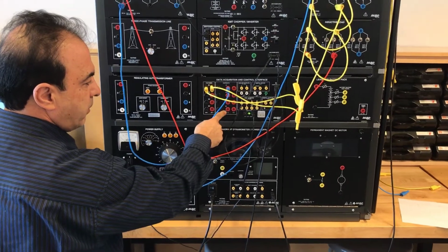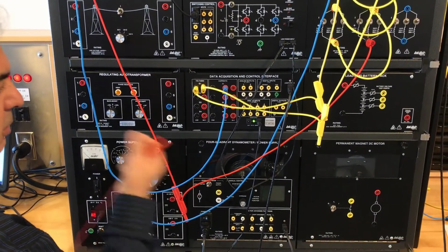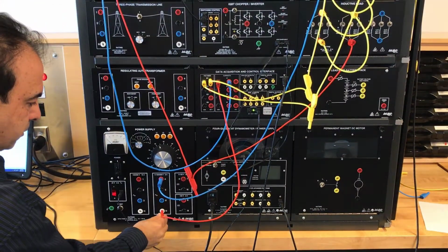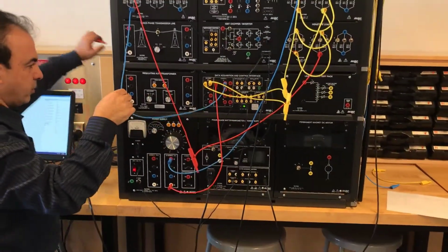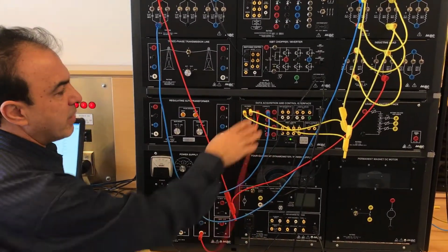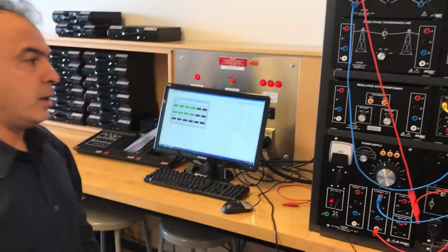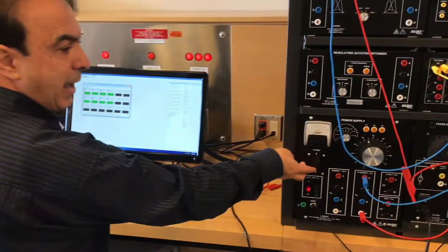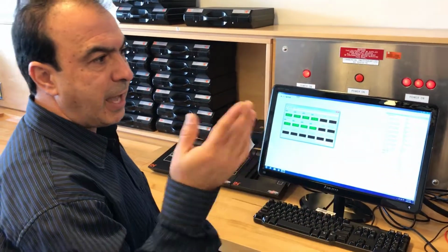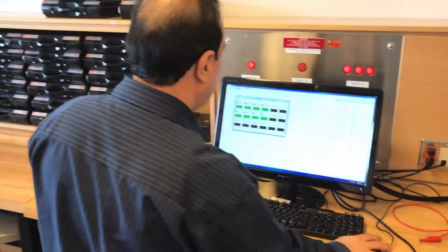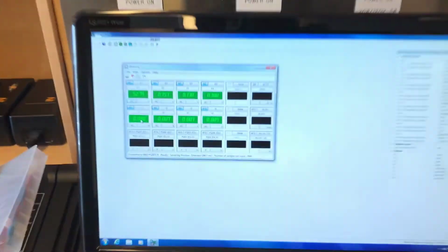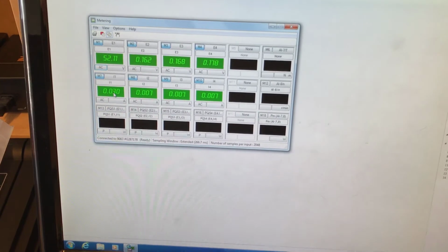So I'm going to connect it to this one. We have 2 different terminals, 4 amp and 40 amp. I'll just go to the 4 amp, and then the other one goes to null. This way, the current meter is in series in the circuit. Now I turn the power back on again. Always make sure the power is off when you are modifying your circuit, adding any meter or doing anything else. Now you can see that the current is read as 0.3 amp or 30 milliamp.